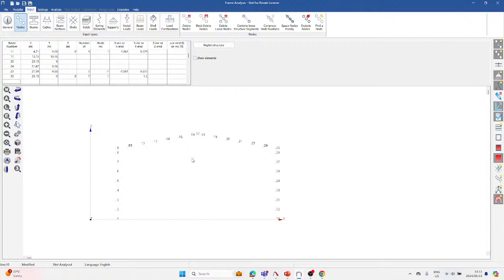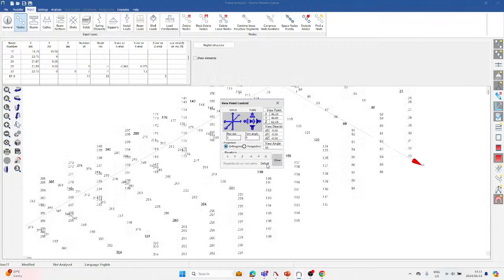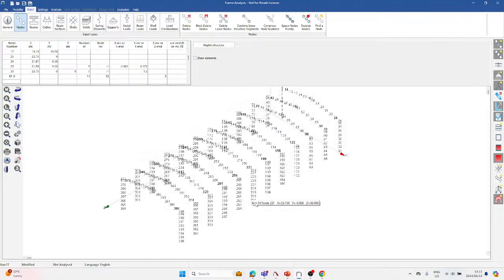So what I do is I'm going to use the block copy function. So I'm going to say B, and I think it's line 1, so you can tell which line it is from the bottom over there. So it's line 1 until line 9. So I'm going to block copy line 1 to 9. Like I said, I want 11 extra bays, and then node increment will be 33, and also I said the spacing between the bays will be 5 meters. Press enter. If I change my view to default, then I have copied over the first portal to have 11 extra bays.